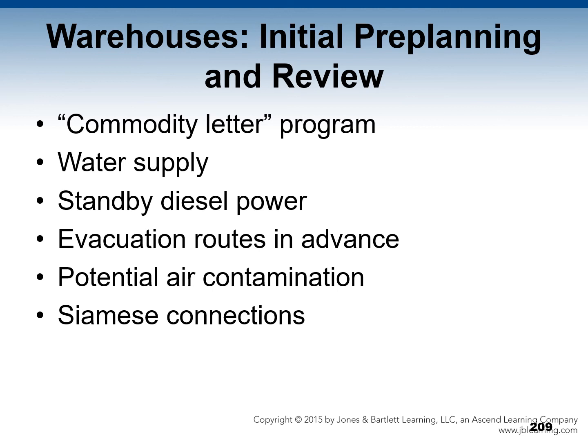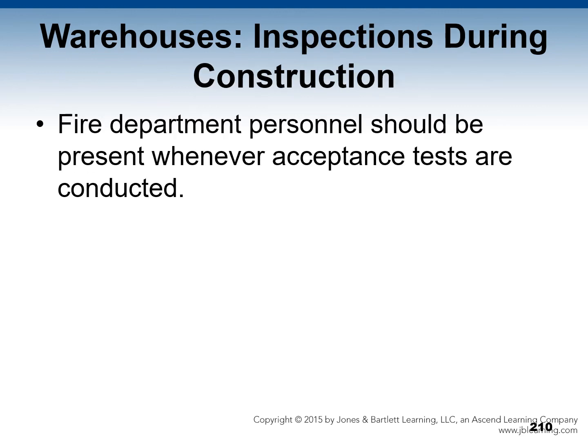And the fire department should insist on fire department Siamese connection availability. Inspections that should occur during construction of a warehouse mean that fire department personnel should be present whenever acceptance tests are conducted.